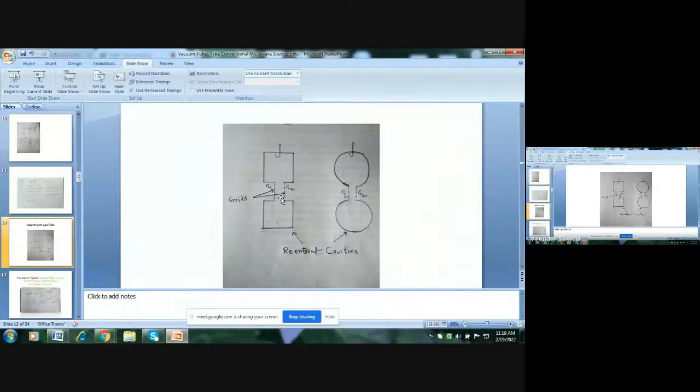the electron beam interact in the cavity. Just as inside a tank circuit, the interaction takes place between the RF field and electrons, and power is transferred in positive feedback. Similarly, in this case the RF field generated in the cavity interacts with the electron beam in three modes. As a result, we get output power. What we have to do? Suppose an electron enters this gap for a small duration, and during that duration the field is in accelerating mode, then the electron acquires energy from the cavity.